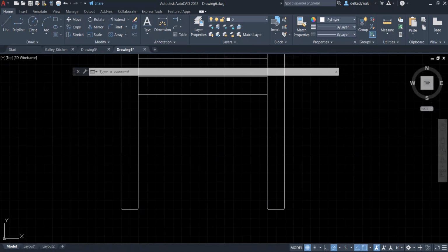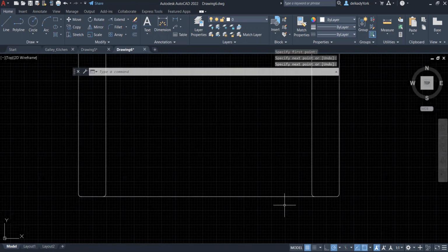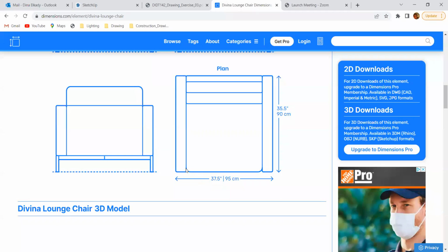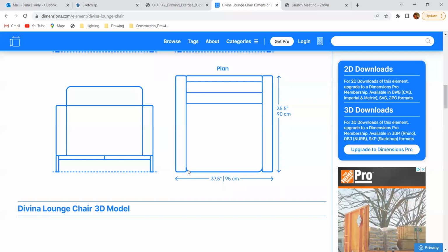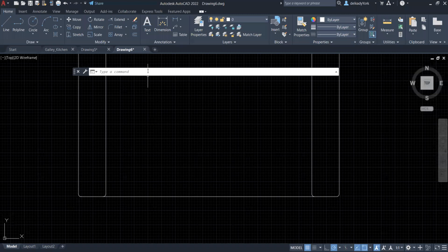Now I have another line here that I need to extend down from here to here, and click enter. And if that precision is needed, I might give this more than this 10, because the radius for the fillet here, I chose 10 millimeters. Maybe this is 20. So this time I'm going to go to fillet, enter, and click on radius. And this time maybe I'm going to use 20. And then click here. I need to extend this first.